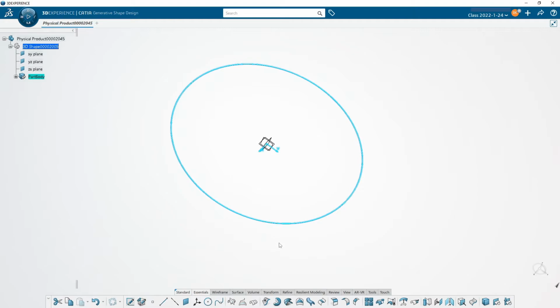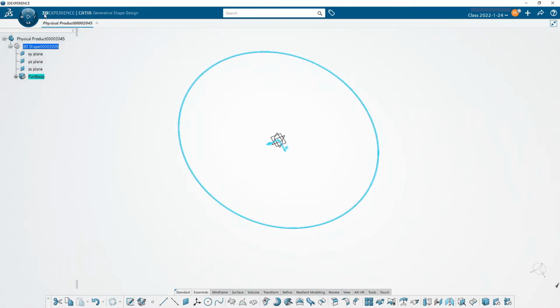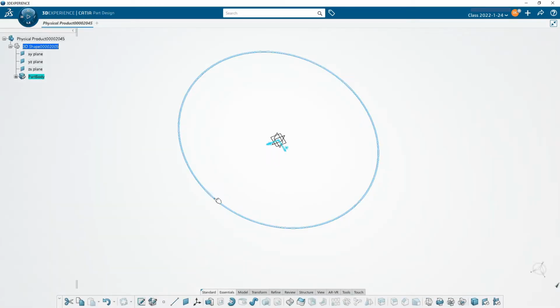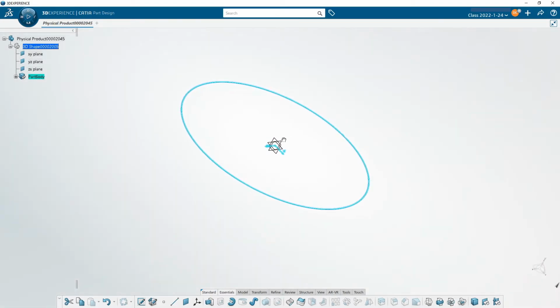And then to extrude this, you want to look along the way here for something that is going to extrude a solid. And so I look at all these things, and if you were to go through what I currently have on here, you go, wait, I don't see that thing I'm looking for, right? If you knew what you're looking for. This is still that surface design workbench that I was mentioning. So I would go, oops, I'm in surface design. I'm going to go over here. I'm going to go to part design. And now my icons change, but like I said before, the part is still here.